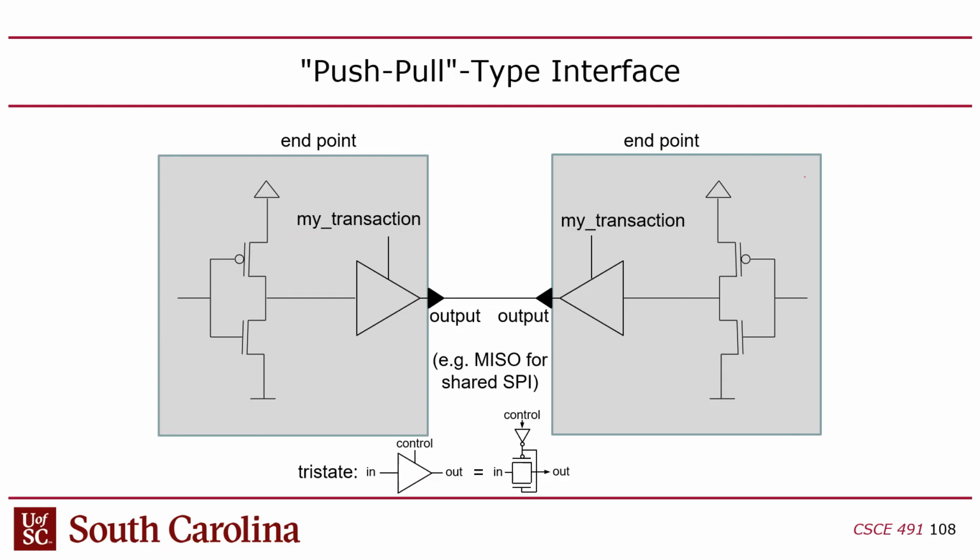Okay, so what do we do about it? Well, what you can do is put a tri-state buffer inside these circuits that allows you to electronically disconnect. You can disengage, right? So a tri-state buffer is just two transistors in parallel, which allow you to basically disconnect. What that means in, for example, SystemVerilog, is that you would represent that through what's called a high impedance. You set the circuit to high impedance, which means I'm disconnecting myself from this wire, and so the voltage on that wire would be floating unless another circuit were to start driving it.